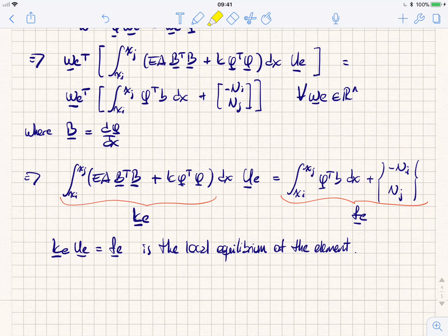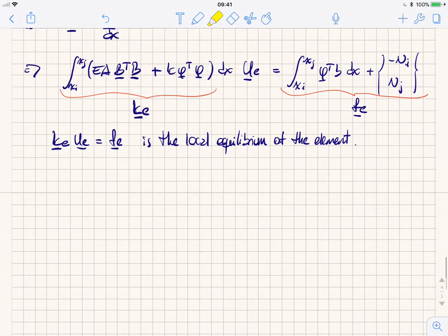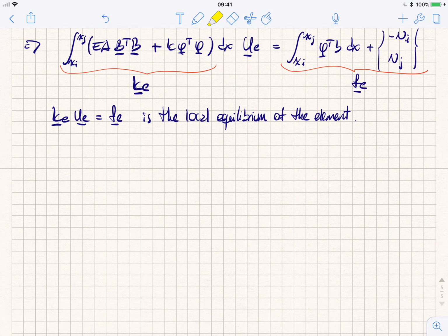So this is one way of approaching this whole finite element story, right? You subdivide the bar, you express the local equilibrium, and then somehow you describe the assembly of all these little components into the big picture. And the missing part to finish this story is to define that assembly, because it's not a summation, it's a special type of sum. So you basically have to sum contributions that correspond to the right degrees of freedom. Okay? And this is called assembly.